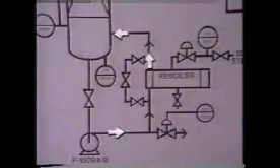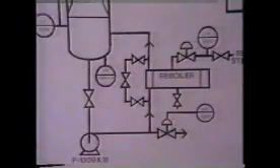The heavier component of the mixture, known as the bottoms product, collects at the bottom of the column. During distillation, this bottoms product is constantly recirculated through a reboiler and back into the column. The reboiler reheats the bottoms product. Recirculating the bottoms product through the reboiler supplies enough heat to the column to complete desired separation of the mixture in the column. When pure enough to meet product specifications, the bottoms product will be drawn off.